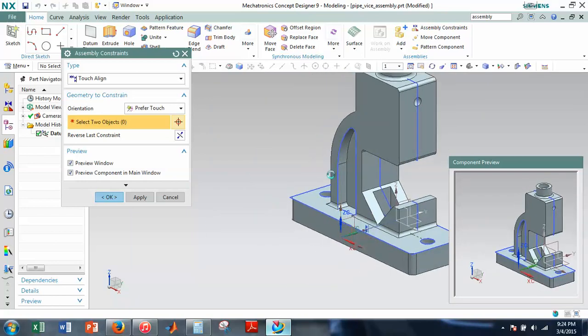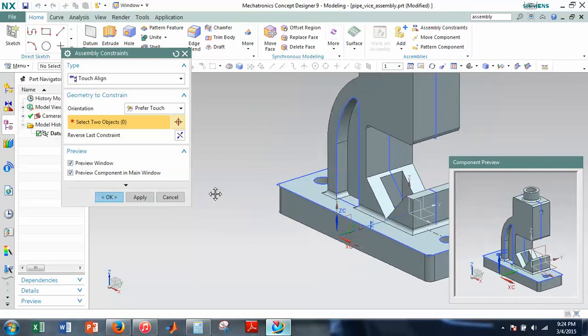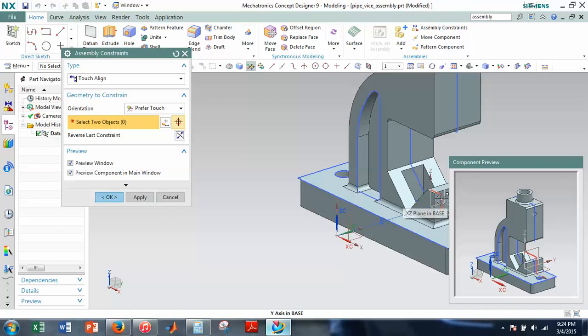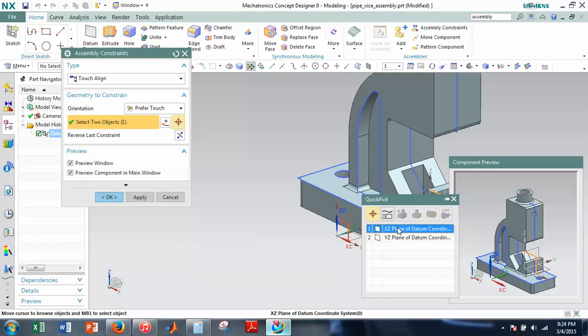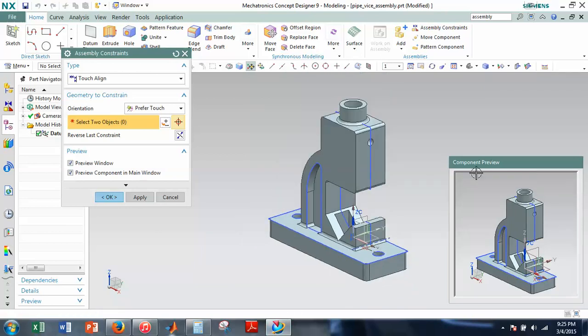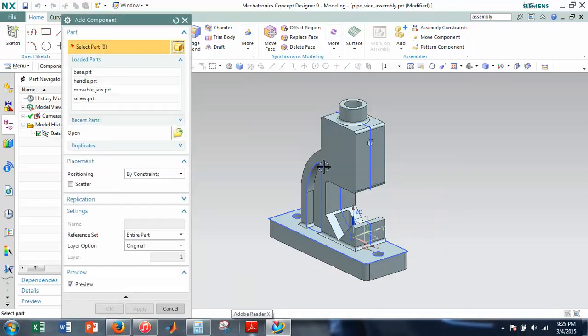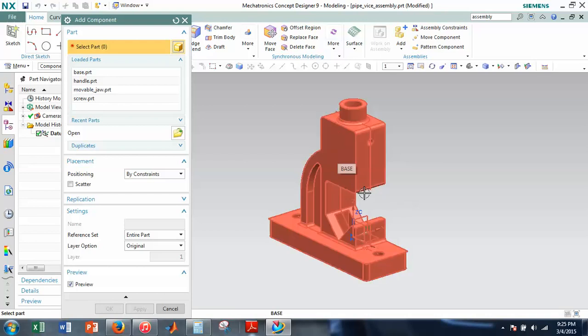To remove the restriction in this orientation, the next thing you would do is select that face or plane, and select this plane. Yeah, that plane. Now if I try to move it, it won't move anywhere. And if I close all these windows out and right click and select show degrees of freedom, it's going to tell me at the bottom that there are no degrees of freedom. But we'll kind of skip that. I'm pretty confident this is staying there.